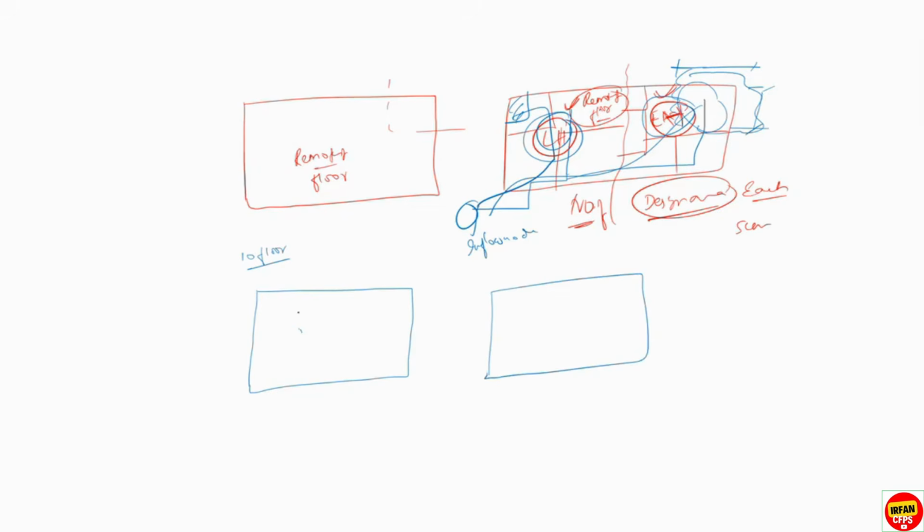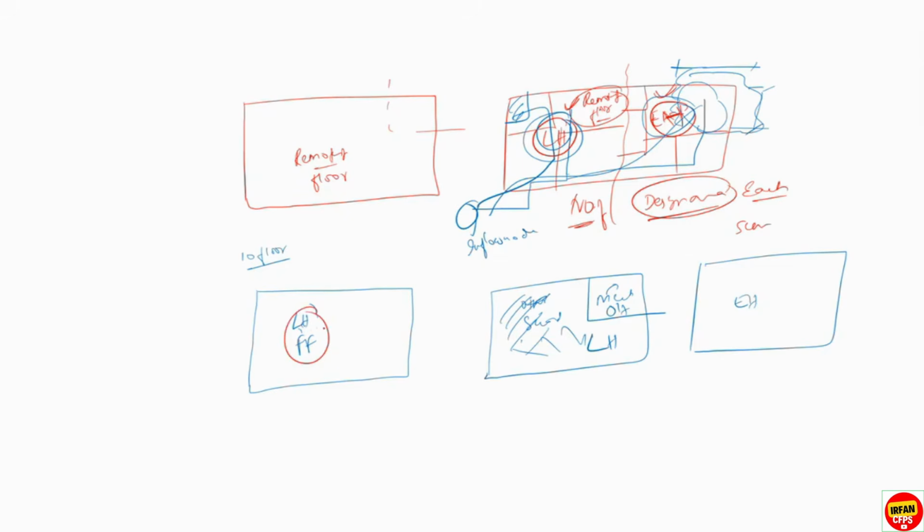Now, assume the first floor and all the other floors are light hazard. In the second floor, one room is a mechanical room, which comes under ordinary hazard, while other areas like offices are light hazard.